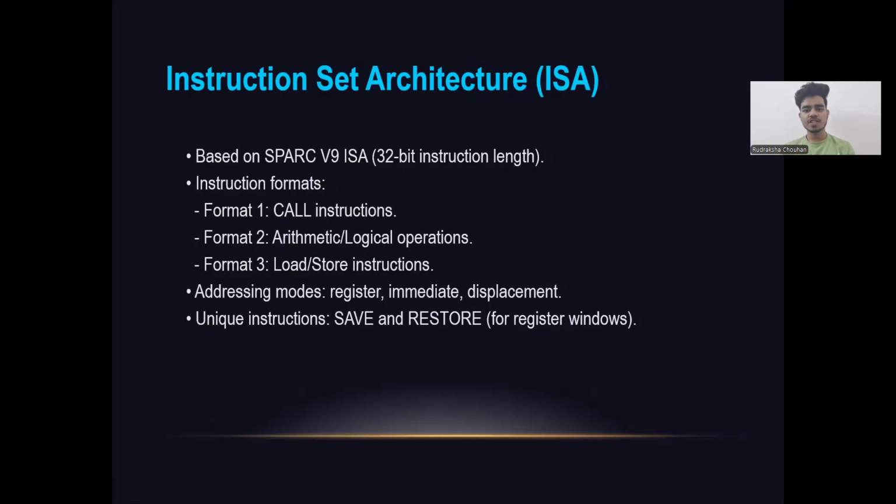Now coming to its instruction set architecture. As I told earlier, it is based on the SPARC V9 ISA, which has a 32-bit instruction length. There are three major instruction formats. Format 1 is used for call instructions. Format 2 is used for arithmetic and logical operations. And Format 3 is used for load and store operations.